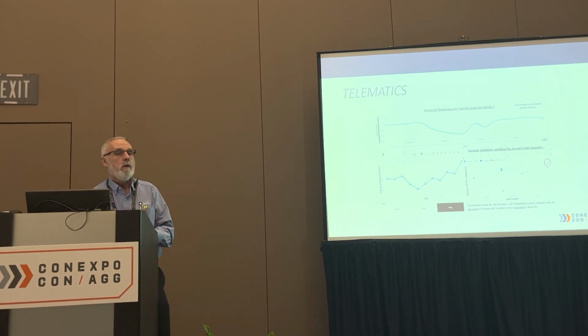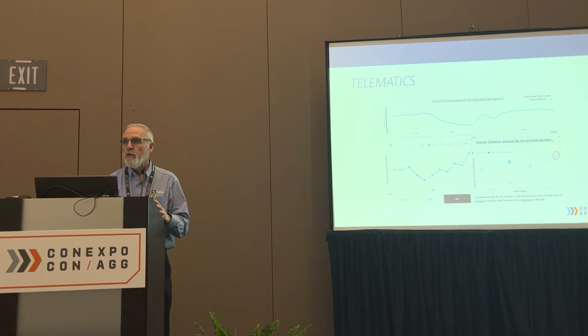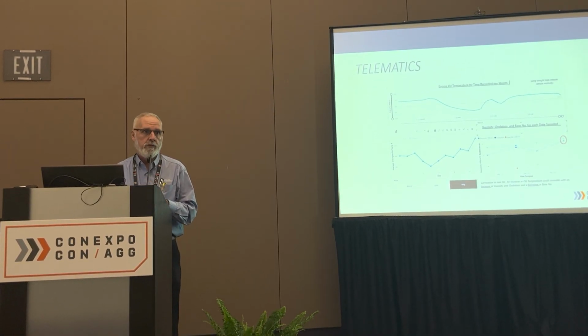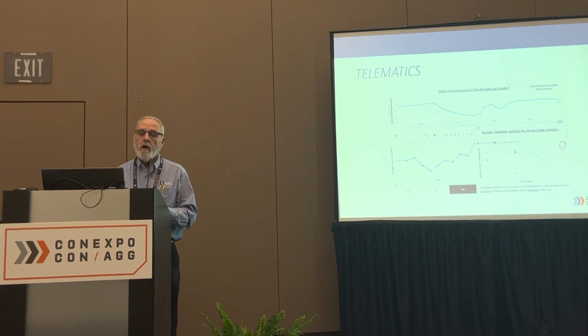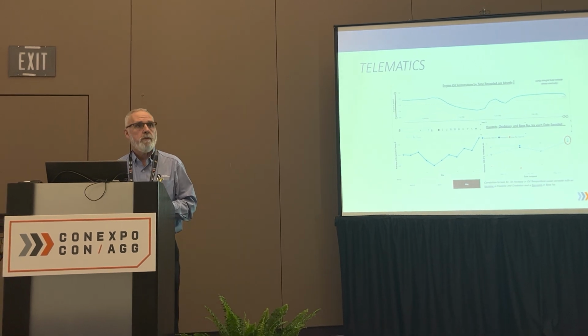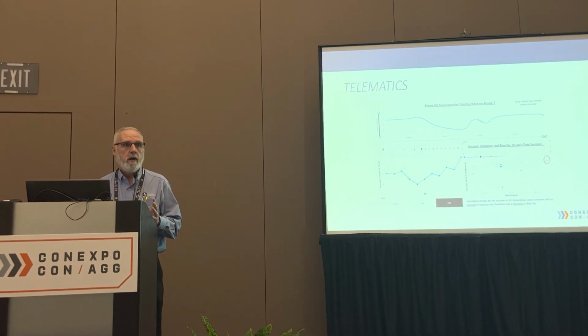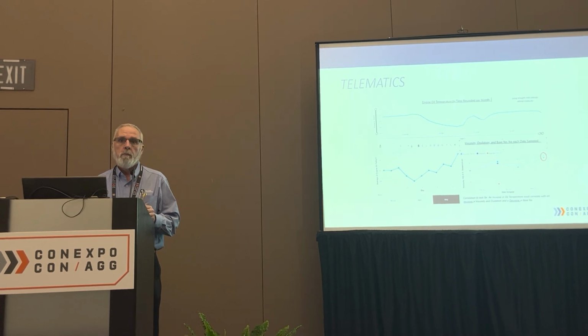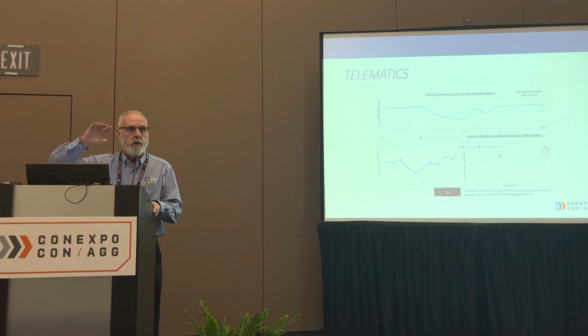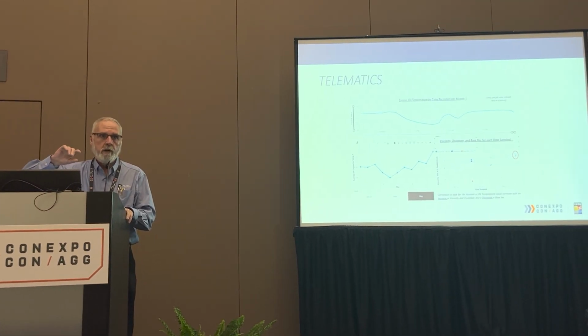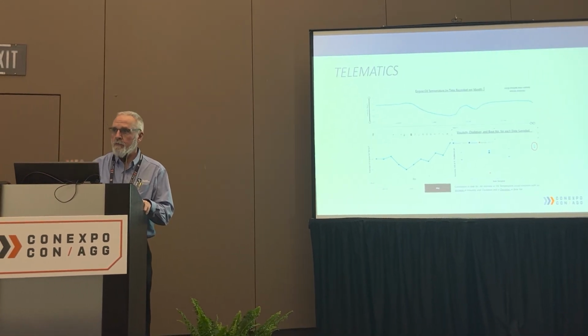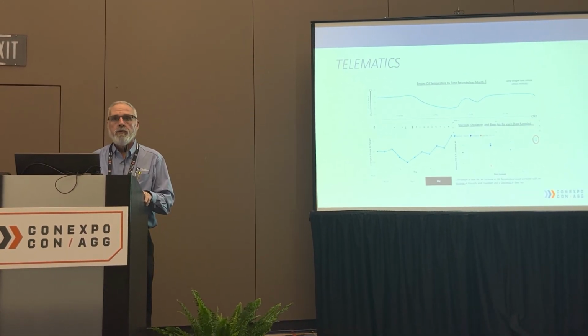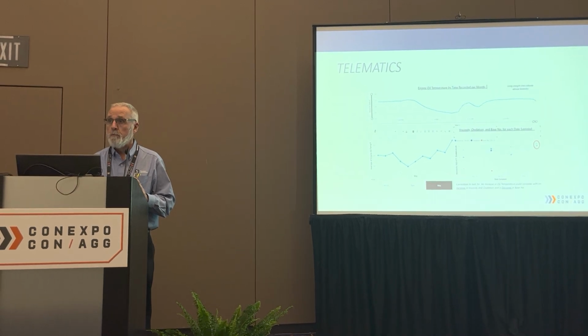And so I combined the fluid analysis results, again, looking at the viscosity of diesel engines, the base number, oxidation, plotted that on a scattergram, but there were some outliers when I looked at that data. There were places where viscosity was really high, viscosity was really low, so I wanted to understand the relationship between that.